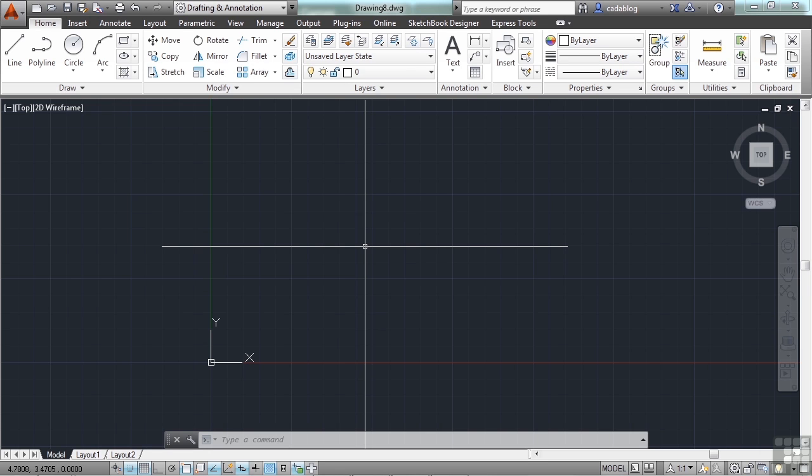If you need to draw objects at incremental units or factors thereof, then snapping is a great way to go. It helps you to draw in these increments every time without doubt and without tedious data entry. The snap technique is not very useful though when you are zoomed way out or you're too far away, because the farther you're zoomed out, the more difficult it will be to see where you're snapping to. So it's a relative thing. You'll have to pay close attention to your coordinates in this case.